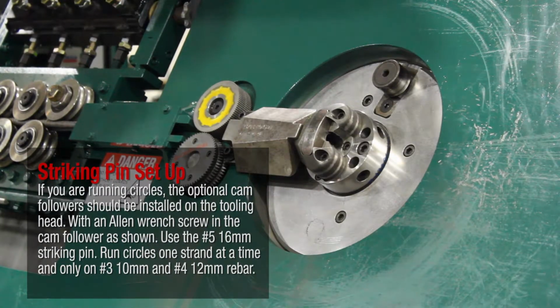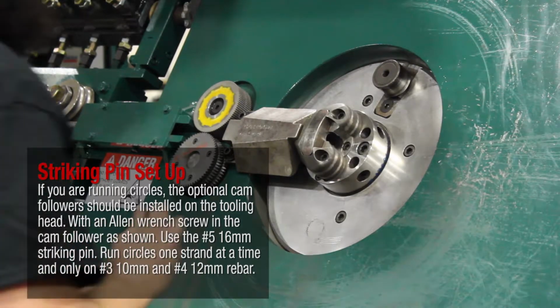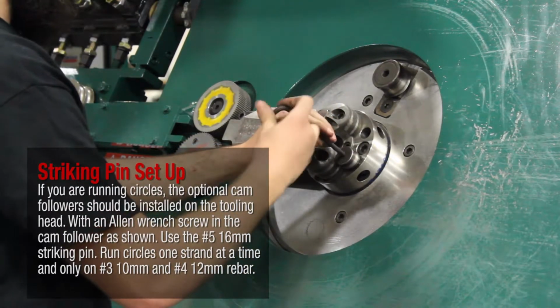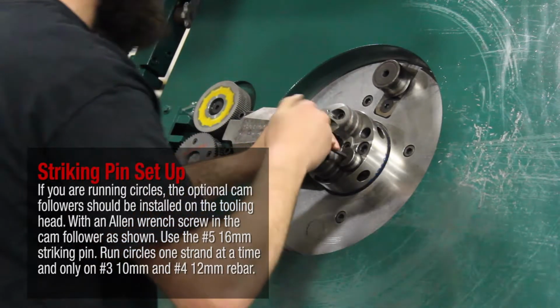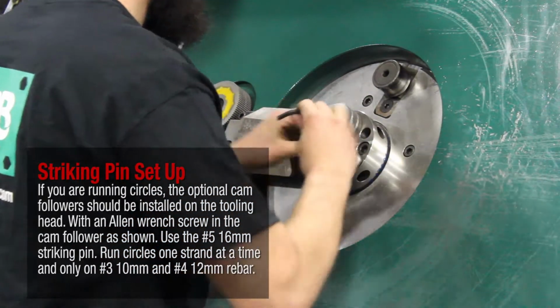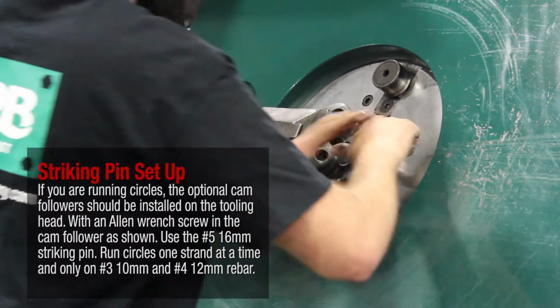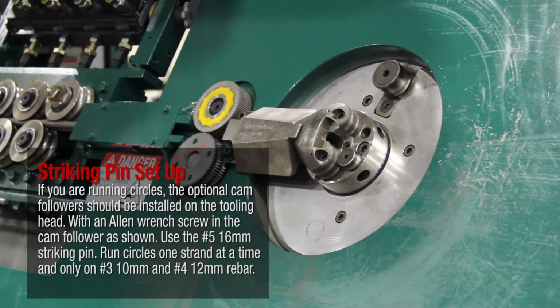If you are running circles, the optional cam followers should be installed on the tooling head. With an Allen wrench, screw in the cam follower as shown. Use the number 5 16mm striking pin. Run circles 1 strand at a time and only on number 3 10mm and number 4 12mm rebar.